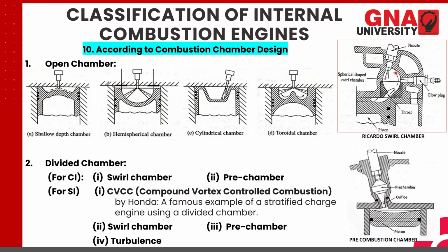You can have a look at this Ricardo swirl chamber, in which the air is coming and entering here and moving in a circular fashion, right? And when it moves in a circular fashion, it enters through this orifice. During the compression stroke, the air enters, moves in this swirling fashion, mixes with the fuel which is injected by this injector, and burns here initially, and then the final combustion takes place inside the cylinder.